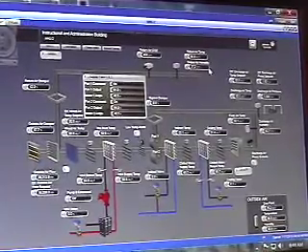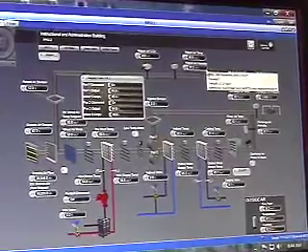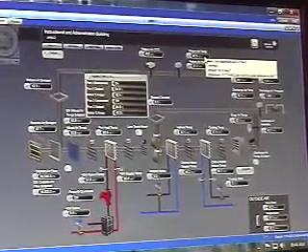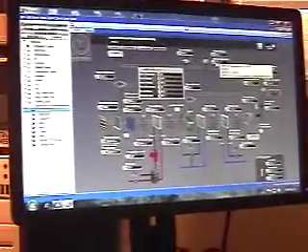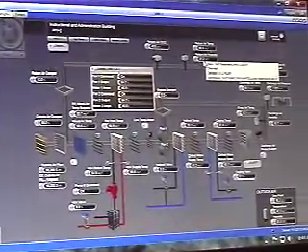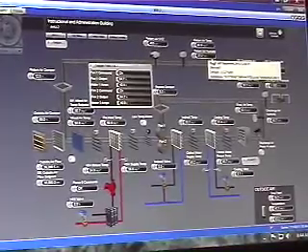So looking at your sensors, you have your return air temperature, return air humidity. Return air temperature, that's just a monitoring point. We're not using it for switching over between economizer and whatnot. That's all done off outside air temperature and state and dry bulb. Return air humidity, that is a sensor that if your return air humidity gets too high and we're running the evaporative media, that will disable the evap media from running.